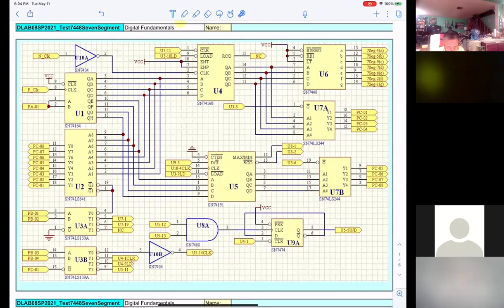Okay, now when you try to load it, pin 1 has to be 1, right? Right. And pin 9 must be 0. Correct. Okay, so that's why you call the function load U4. They will be automatically set for you, pin 9 to be 0, so pin 1 will have to be 1. Okay, so does anything need to be done with U3B, pins 10 and 11?